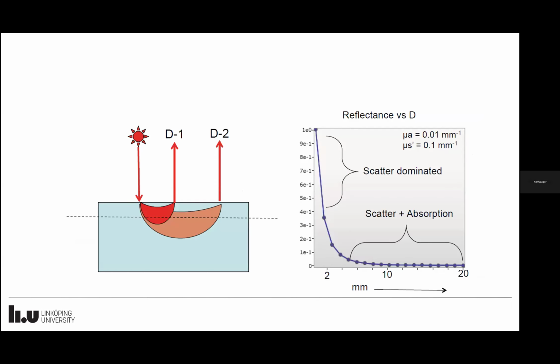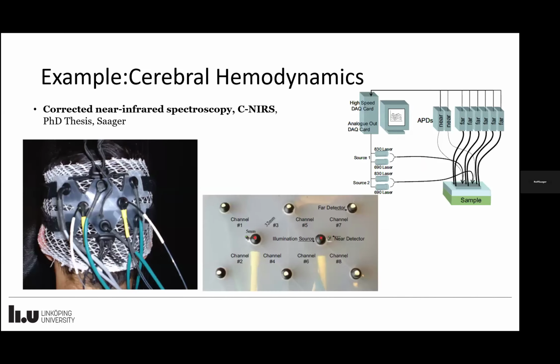So again, the large take-home messages, and the things that I had experienced, especially with instrument design, is even though it's simple and low cost, trying to do multi-depth sampling and multi-distance measurements with this, what I always encountered was the fact that there was such a large differentiation in dynamic range that you had to play a lot of games to really balance signals, maintain signal to noise in these types of setups. And so, going back to this, we had the original idea that we had these large fiber bundles in the far source detector, a small fiber for the short, so we could try to balance the signals.